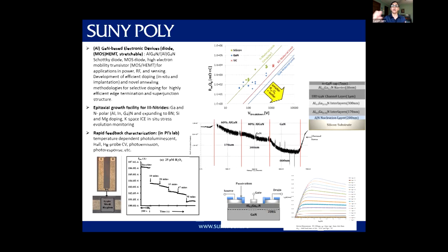From there, one device that is used in that type of switch application is the high electron mobility transistor. On the right, you see the layer structure from the silicon substrate all the way to creating the HEMT itself. The HEMT itself is really just gallium nitride on top, then a very thin layer of aluminum gallium nitride, and then it's capped.